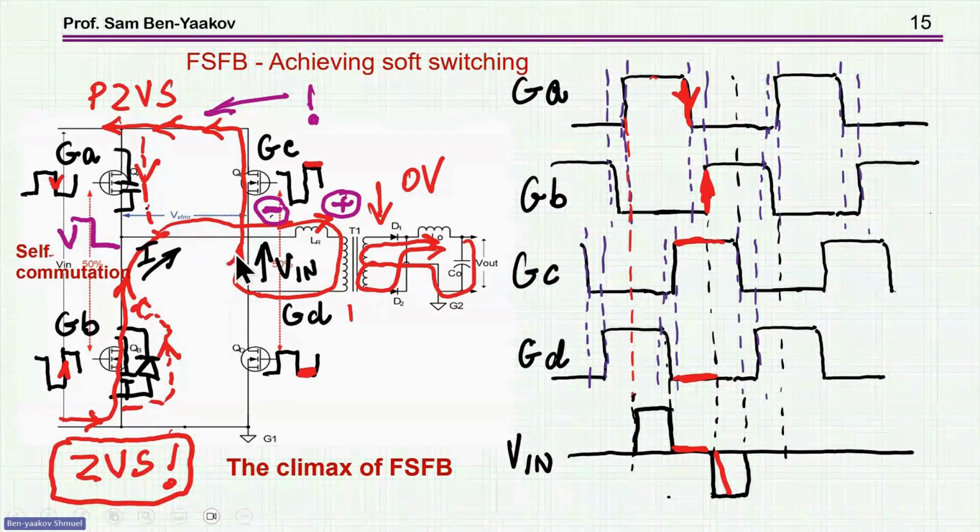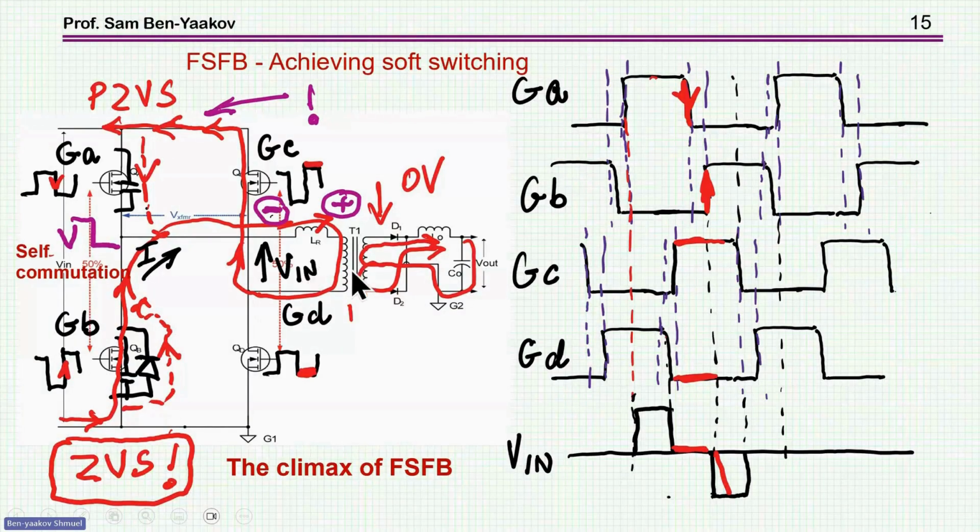Now, this reversal is temporary because now we have a situation that the output is zero, there is the current, but notice that on this inductor now, the plus is this one, this point here, the minus is this point here. So the current, the IDT is in this direction.